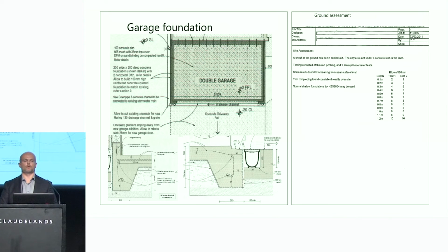And so one of the problems that we did see with the drawings was that some of them were quite difficult to read. And so try to draw your stuff in the way that the builder's going to be building it. The builder's not going to be building your beams first or your roof bracing, so don't put them at the front. He's going to be starting with probably your retaining walls and your foundation system. So put those at the front so that they know what's going on.